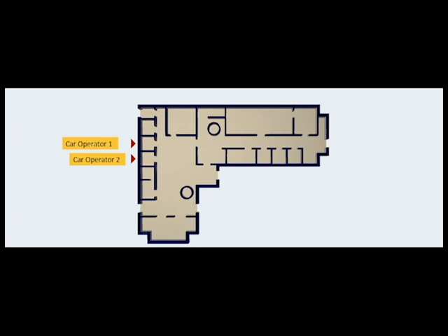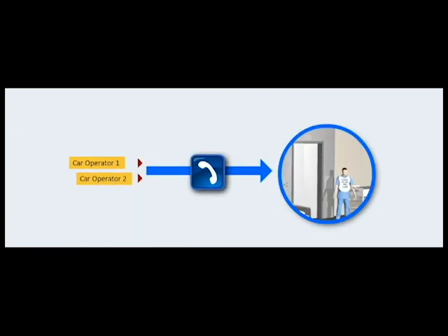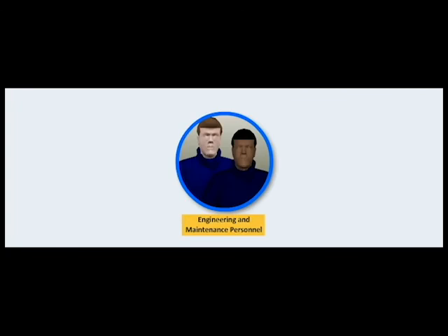Designate elevator operators by car number and communicate with the lobby elevator controller primarily by the assigned radio channel or secondarily by the elevator car phone. Elevator operators control their assigned elevators through the use of the firefighter's override key and carry out the movement orders of the lobby elevator controller. When available, dispatch additional engineering and maintenance personnel to assigned floors to evaluate the egress path from an affected area. It is their job to make sure the path is maintained and unobstructed.